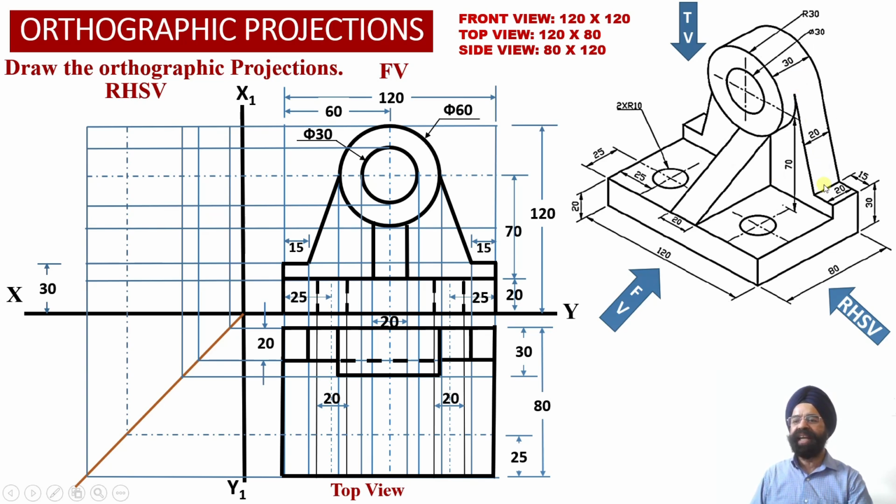corresponding to this inclined surface and this inclined surface, because these two inclined rectangular surfaces happen to be inclined with respect to the horizontal plane, we are able to obtain a foreshortened apparent shape rectangular projection onto the horizontal plane, obtained on the right hand side and on the left hand side projections over here into the top view projections.